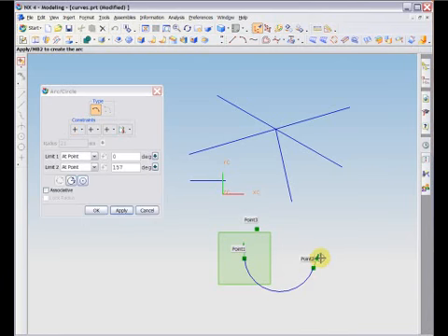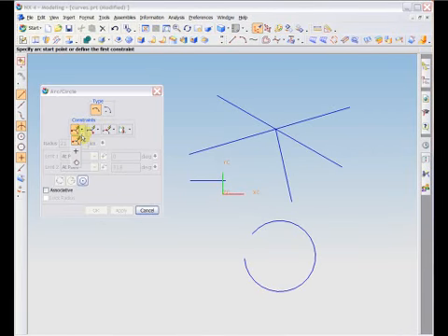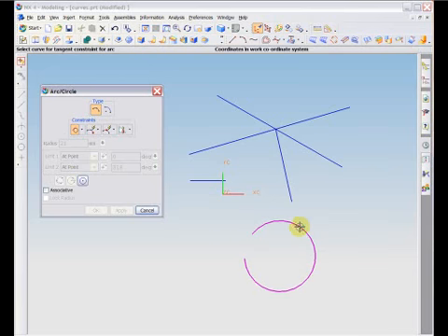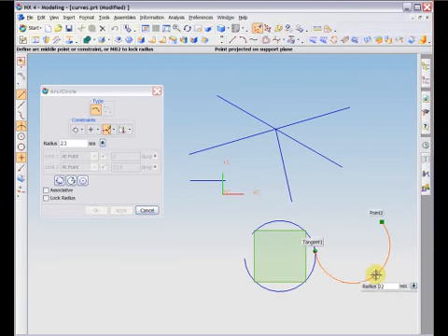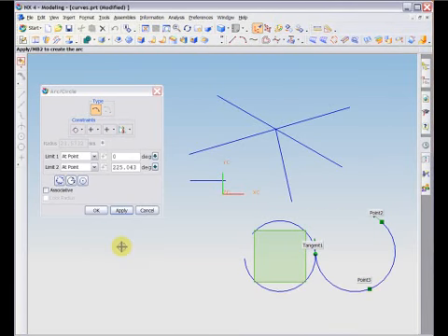Also, as in the Line command, the Arc command allows you to constrain the endpoints. For example, points can be constrained to be tangent to a pre-existing arc. After choosing this option, you simply need to select the arc you would like the new arc to be tangent to. You may then be faced with more than one solution which would fulfill the required tangency. You can examine these options by clicking the Cycle Alternate Solutions button.